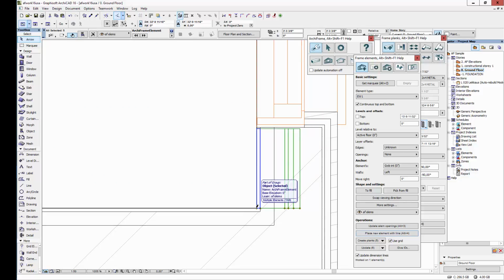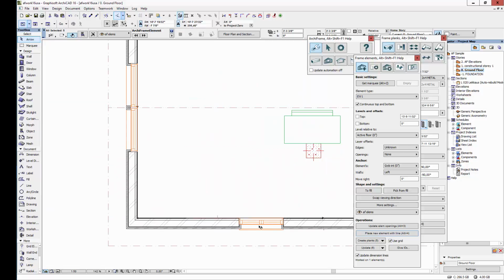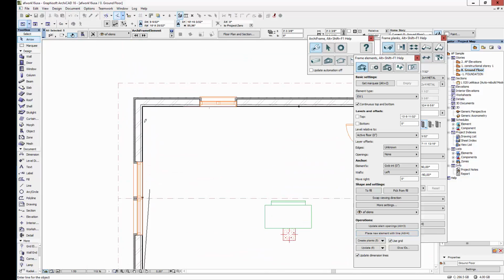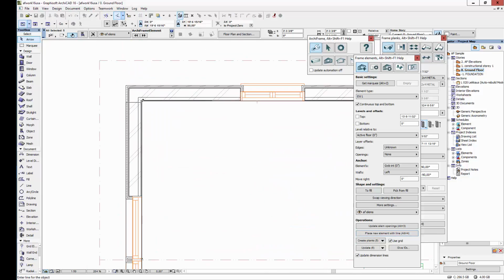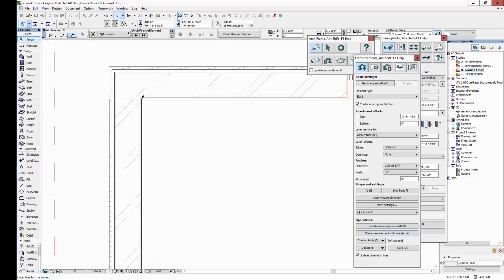And as you can see, the element type and the final wall, they don't match. It doesn't matter, you can use different types in ArchiFrame compared to the architect model. Okay, I will add the other gable wall the same way, and notice my line direction for the walls looks from inside. The external walls should be made clockwise. The watching direction is always on the right hand side of this line.